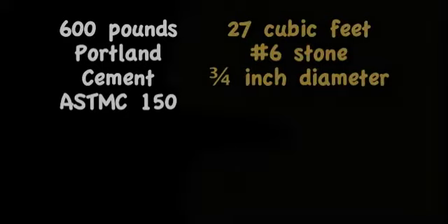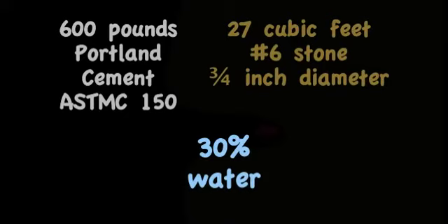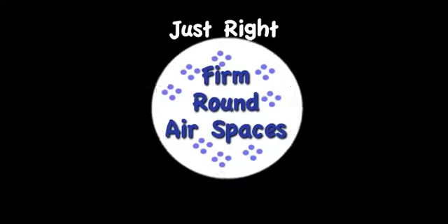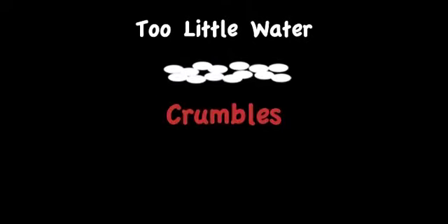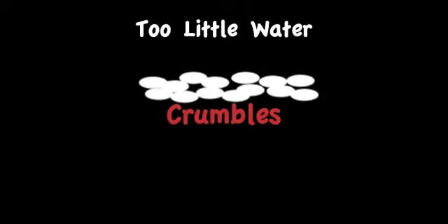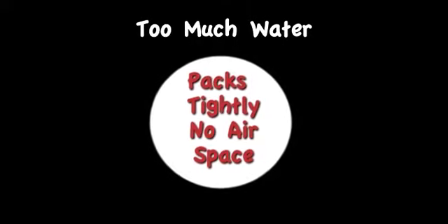For example, mix 600 pounds of Portland cement ASTM C150, 27 cubic feet of number 6 stone, 3/4 of an inch in diameter, and 30% water to cement mix. The proper amount of water varies considerably, but getting the right mix is critical to the success of the permeability. If mixed properly, a handful of pervious concrete formed into a ball will not crumble. Too little water and the ball will crumble. Too much water and the concrete loses its void structure.